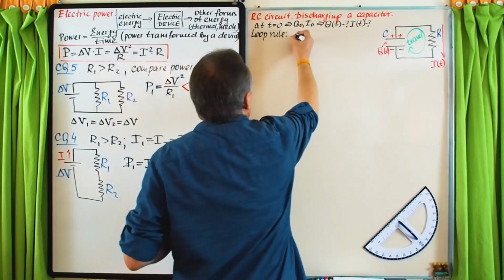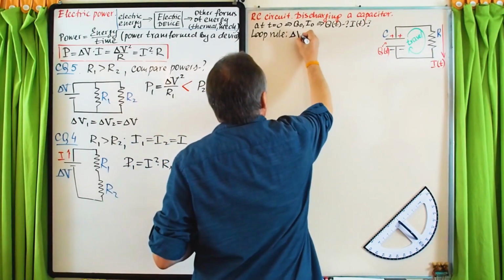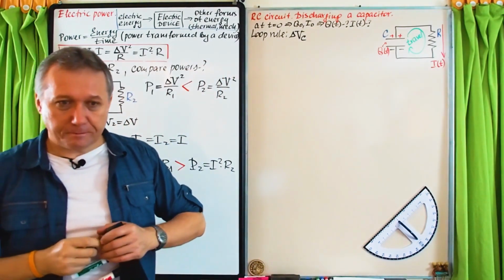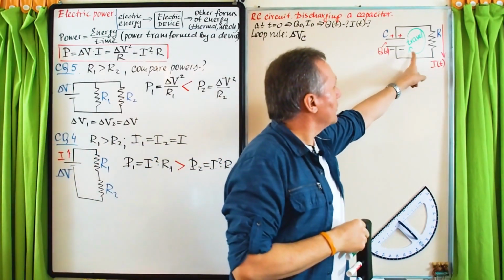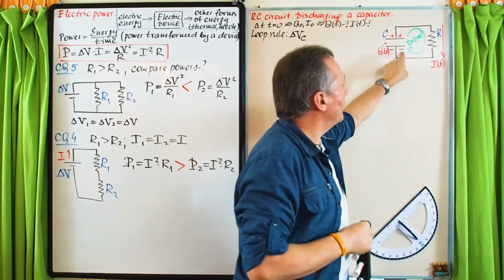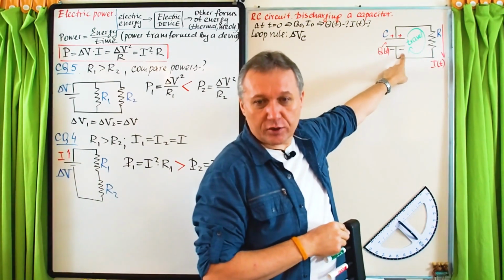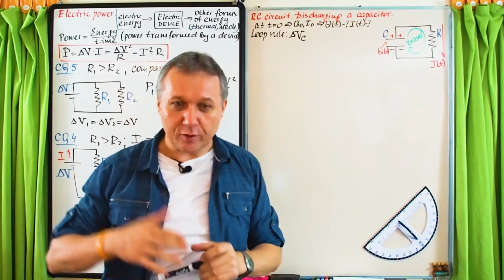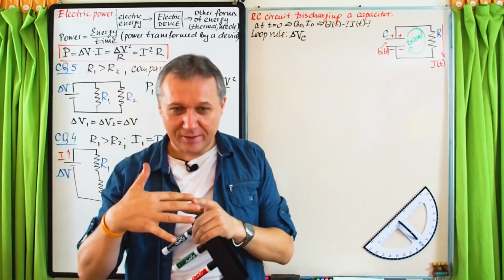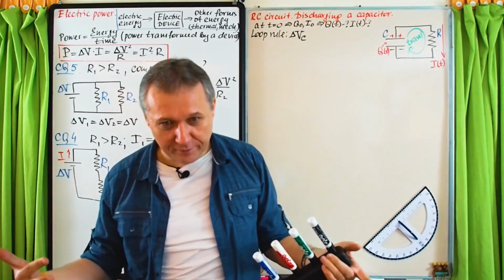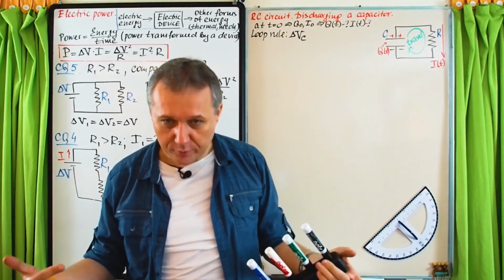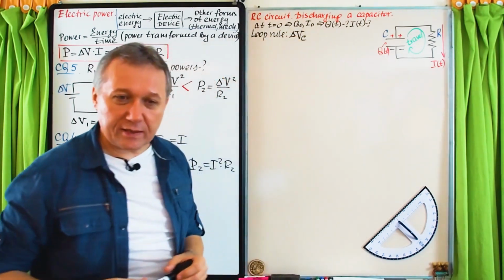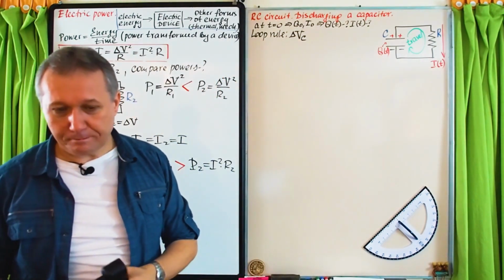So first, potential difference across a capacitor. Is it positive or negative? Look, we travel, you see, that way, clockwise. So first, we are here, that's initial point, negative electrode, final point, positive electrode. So V plus minus V minus, potential difference across a capacitor must be positive. That's why I put here a positive value, plus delta V sub C.